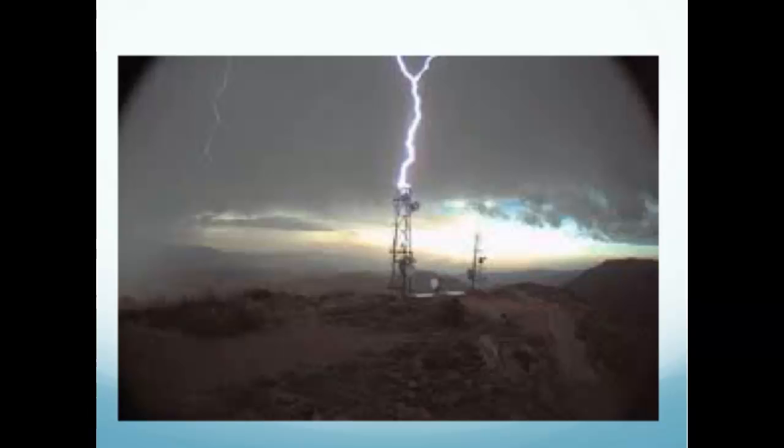So we put wireless cameras on top of the silos. On day 3, I noticed that we couldn't see anything out of those cameras. It looked like it was foggy all the time. I'm watching them from a distance saying, wow, it's really foggy at the farm. And then I started looking at the weather and there was no fog. The heat from the silage was rising up and getting into the workings of the camera. It wasn't sealed well enough.